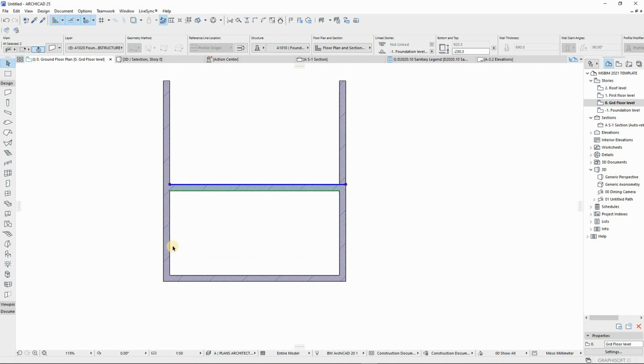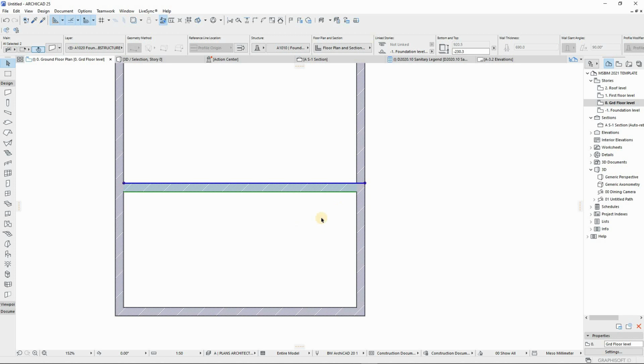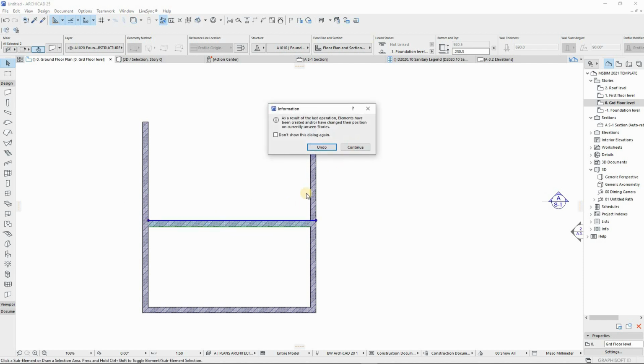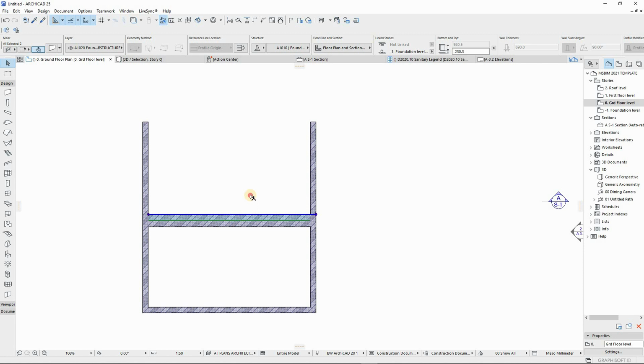to create a bedroom and a sitting area this side. And then I'll also duplicate this like so, and then move it there by the width of the toilets, say 1.2, enter.